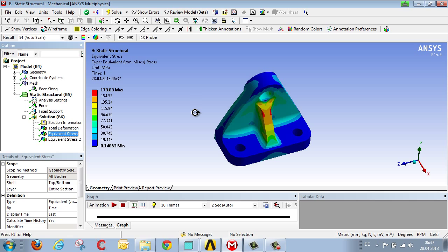Just to complete the picture regarding the quality of the mesh, it's now sufficiently accurate for production of a reliable stress report. Once again, let's compare the stresses that have been averaged out with those that have not. When the values are virtually identical, we have fulfilled the criterion of being able to ascertain that the mesh is of sufficient quality, sufficiently accurate for production of reliable reports.